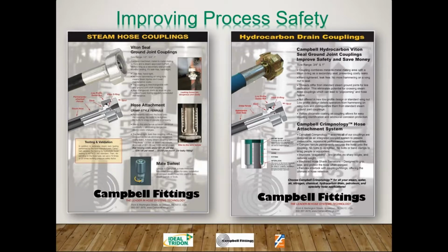Improving process safety with the steam hose couplings and hydrocarbon drain. Hydrocarbon drain is on here because, especially in the refineries, it's basically a sister application to the steam. Unfortunately, it gets crossed quite a bit. So you'll see steam hose in a hydrocarbon drain application and vice versa.